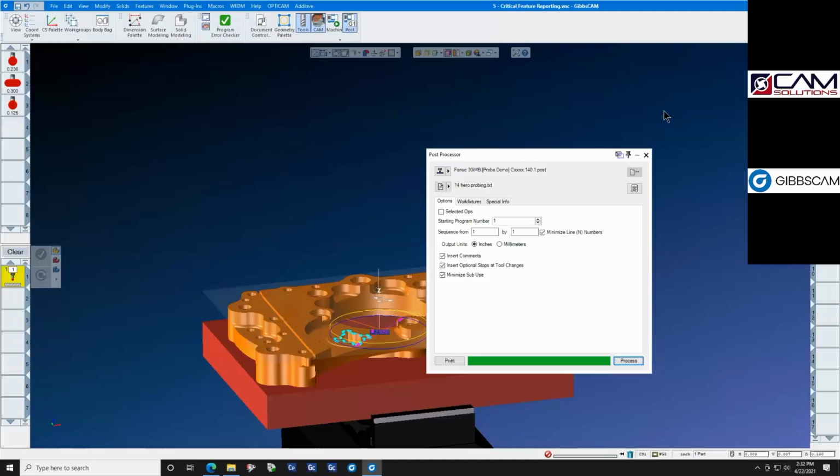And the summary of today's webinar is the profit impacts of in-process probing, and this is what you can expect. The part and tool setting, reduce part and tool setting times by up to 90%. Probing is now automated and is more repeatable than manual methods. A more reliable setting process means less downtime once production starts.